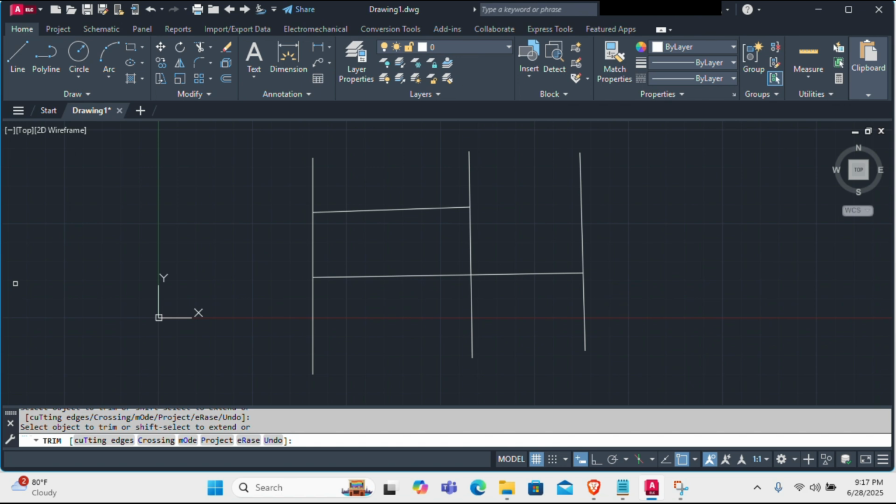So now what are these use cases in electrical drawing? They are used for cleaning up ladder diagrams, extending wires to symbols or connectors, cutting unnecessary wire jumps, finishing incomplete busbars or terminal strips. These small touches make our drawing readable, complete and professional.